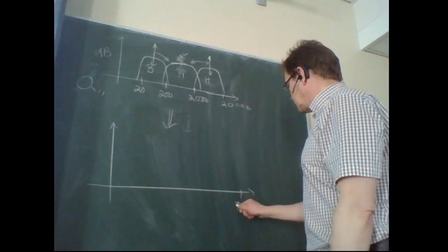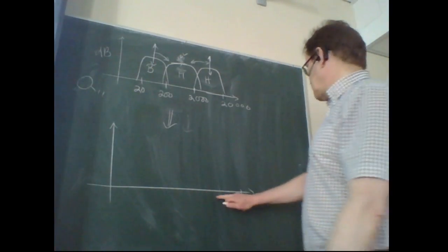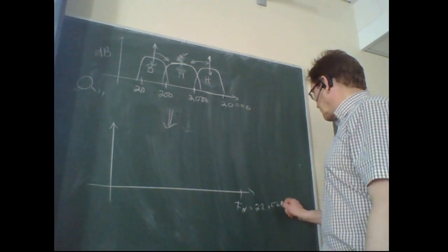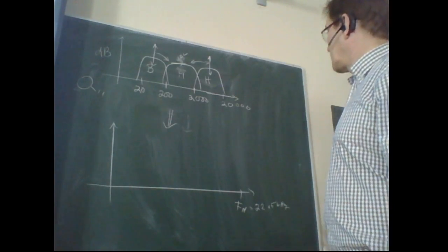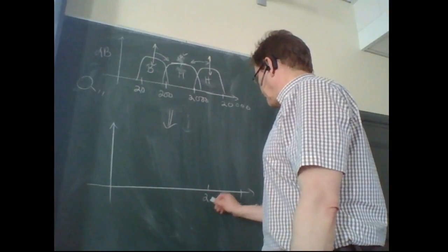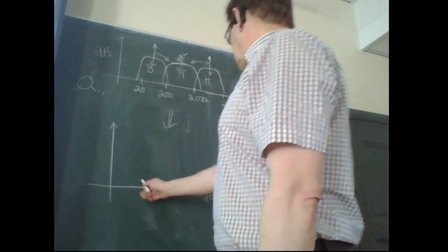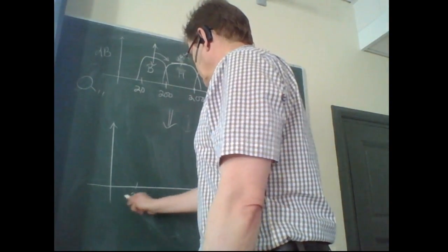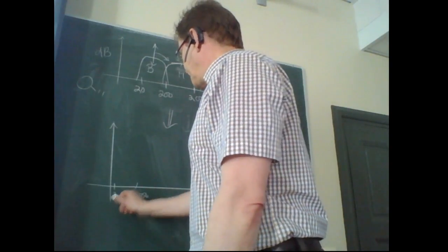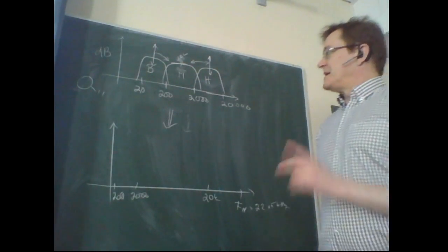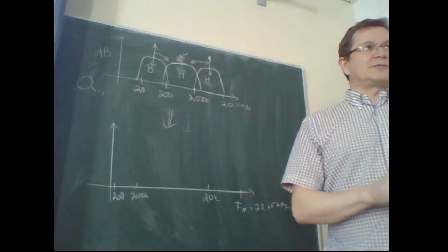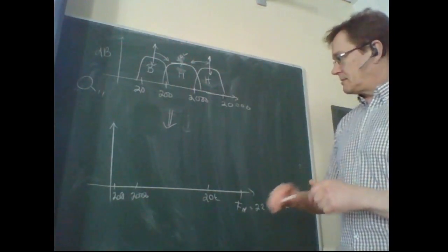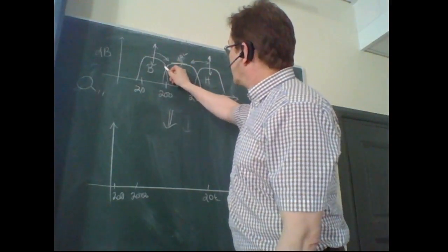First of all, we have the Nyquist frequency. If this is, say, 22.05 kilohertz for 44,100, then this 20,000 is here, and 2,000 is somewhere here, and that's about the 200. All right. So when you're designing a filter bank for digital filters, you still need to think analog, especially on these overlapping zones.